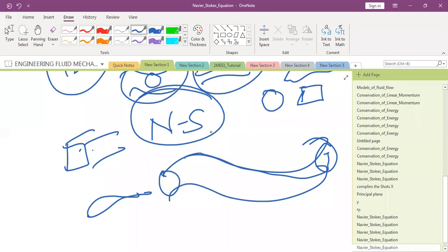So the Navier-Stokes equation is called the cornerstone of fluid mechanics, because if you have understood this equation, you can formulate other equations by approximating certain terms to zero. For instance, the Poiseuille equation, Couette equation, Euler equation, Darcy equation, any equation you name. So I will break for today and we will continue with this.